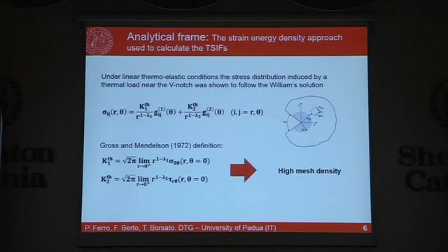The main drawback of such a definition is that one has to calculate the stress distribution using a very fine mesh, a mesh with a very high density of nodes and elements, because this high density mesh is necessary in order to obtain the asymptotic distribution, to capture the singular behavior of the stress distributions.